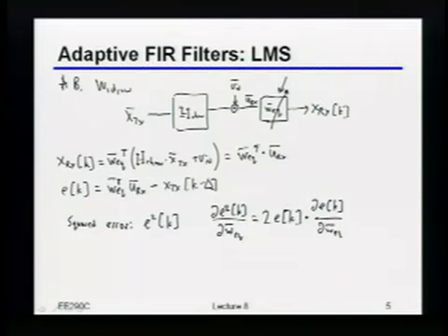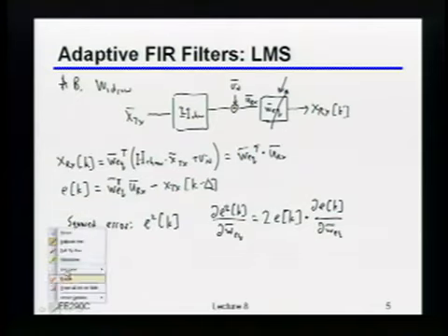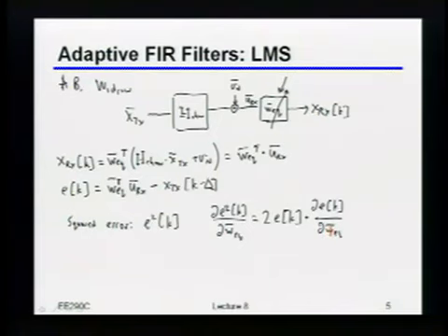Well, notice, what is the derivative of the error with respect to my equalizer coefficients? What is that? It's u_rx. Yeah, it's just u_rx, because if I take the derivative of this with respect to the equalizer, my transmitted bits hopefully have absolutely nothing to do with my equalizer coefficients.